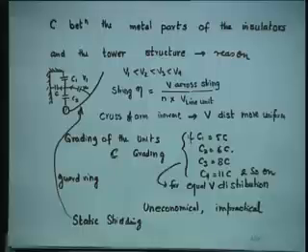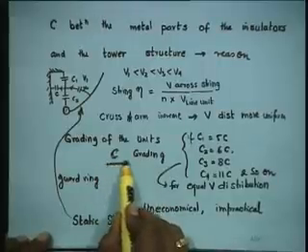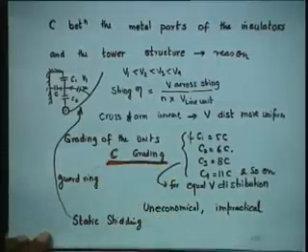But if you do this, this method of grading is called capacitance grading. If you are adamant, you say no problem, I have a lot of money, I have a lot of space, I will store them, then such a method is called capacitance grading. This is what I have written here, and you will have a perfect voltage distribution, equal distribution.